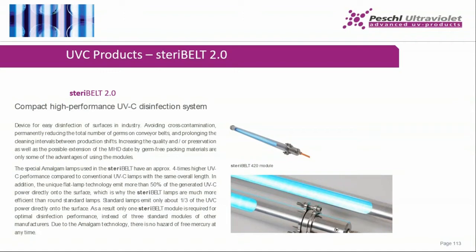This is conveyor belt disinfection. That means if you have a deboning line or transport belt, you have a really high risk of cross-contamination of such conveyors. During the working process, you have no chance to clean the belts. You only have a chance to clean the belts during a break. With UV, when you mount it on the underside of the conveyor, you can disinfect it really simply during the process. We have many independent tests and reports for the results of this disinfection during a working process.